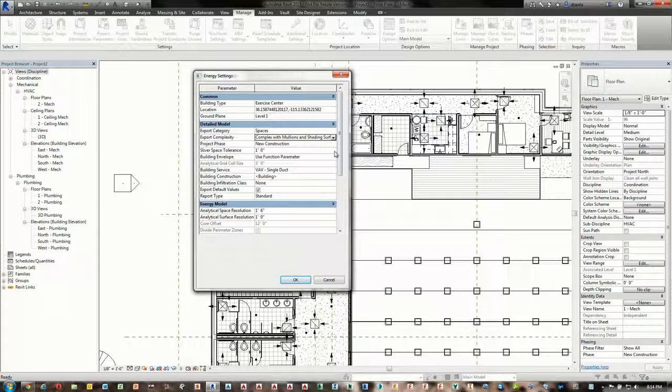This is where you're working and you've got, say, two spaces, and maybe it's a chase wall, or maybe it is a plumbing wall. And that plumbing wall internal distance is greater than a foot. If that number is greater than a foot, which is the default, then you'll get a warning from Revit saying, hey, do you want to include a space object to account for this space?